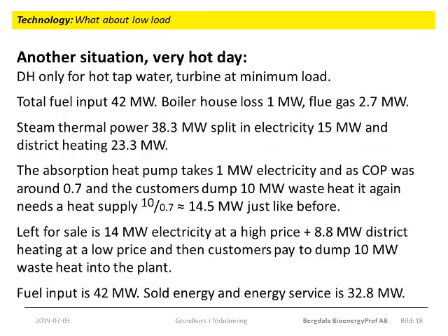So while the previous case was at high load, let's now look at a low load case. Let's look at the balance on a hot day when the district heating is used only for hot tap water, which is less than 10 megawatt. The turbine can only be down regulated to approximately 15 megawatt. So the turbine efficiency is now slightly lower, and so is the total efficiency. Looking at this slide, you will understand how the calculation is done, and this is the type of calculation that you will do in the homework.